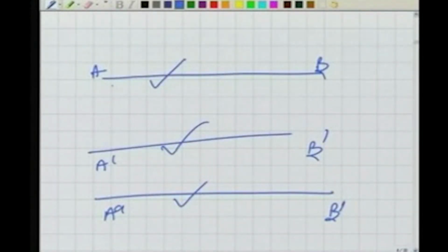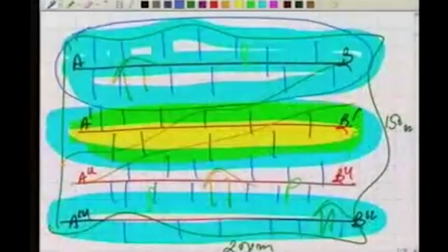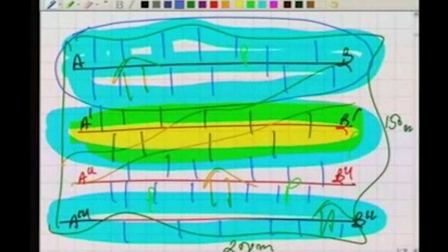There has to be some measurements which connect these together. If you cannot connect it, where to plot it? So, relatively they should be fixed in the ground. So, we can go for a thing like this, but we need to take some extra measurements there which relate this chain line to this chain line and this chain line to this chain line, so that we can fix them relatively also, and this is how we can plot the area.